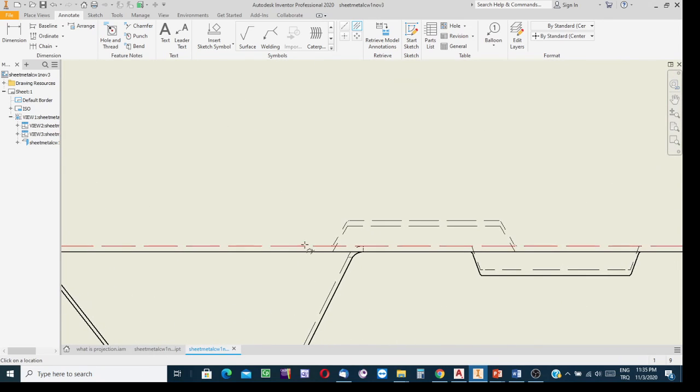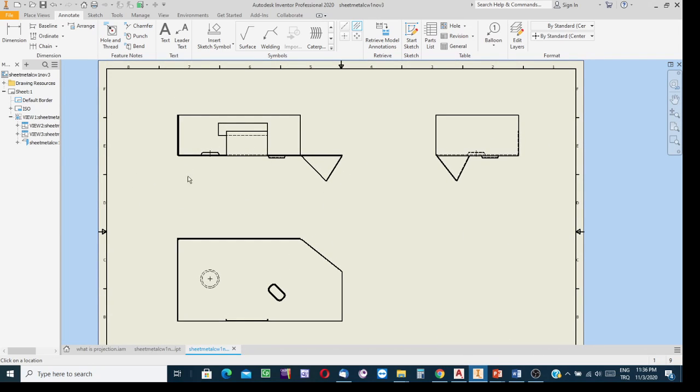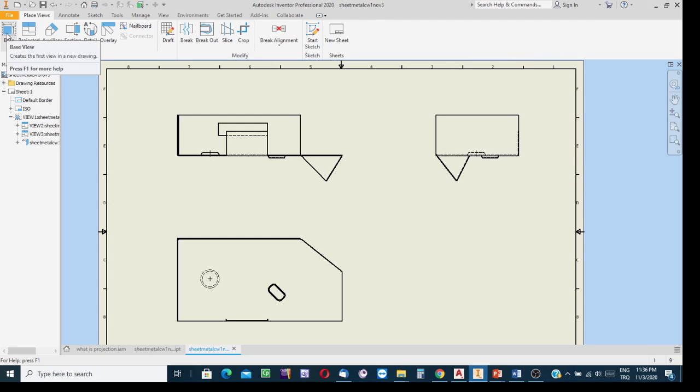Okay, for this one on the left side view, show the longitudinal axis by indicating these limiting surfaces. Okay, and then, of course, show the dimensions: width of the object, depth of the object, height of the object, and the location dimension for this one can be shown on this view. But show such things on the development. Actually, the location dimensions for the features show the measure of the location dimensions, and of course the size dimensions on the development.